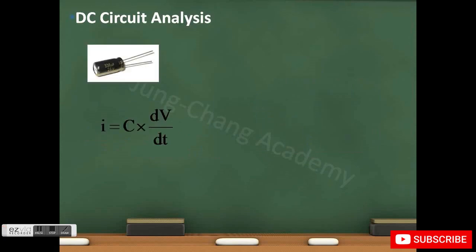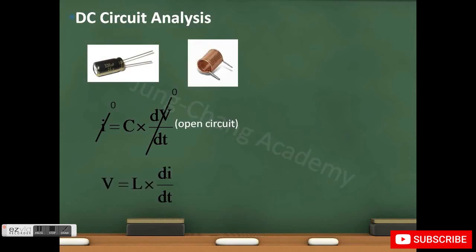the current is equal to the change in voltage times the capacitance. Since a DC supply has a fixed voltage, the current flowing through that capacitor will be zero. In other words, the capacitor will look like an open circuit. Similarly, the voltage across the inductor is equal to the inductance times the change in current. Again, since the DC source supplies a constant current, the voltage across the inductor in this case will be zero, meaning the inductor will look like a short circuit.